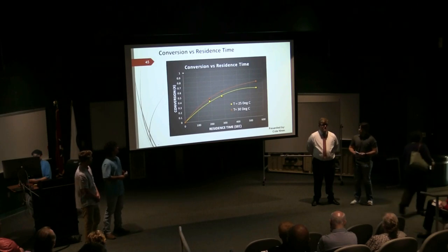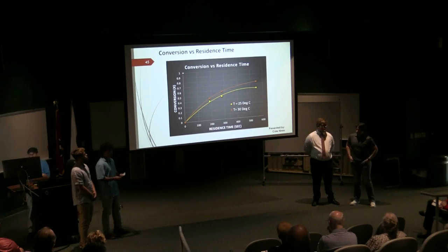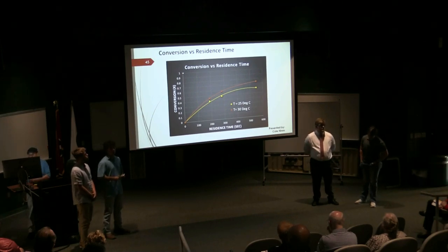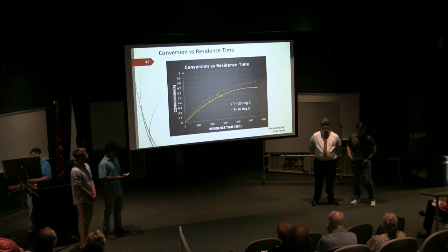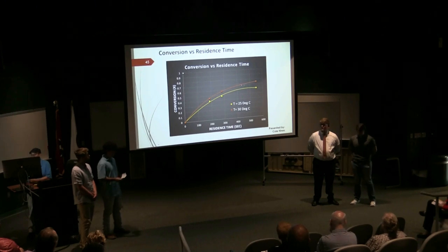So here you can see that an increase in temperature means an increase in conversion. Conversion levels off as residence time increases. Our optimal residence time for the temperatures we ran was between 400 and 500 seconds.